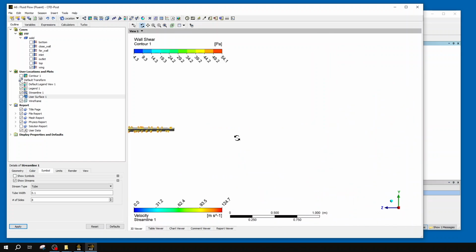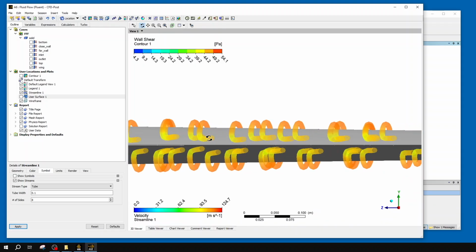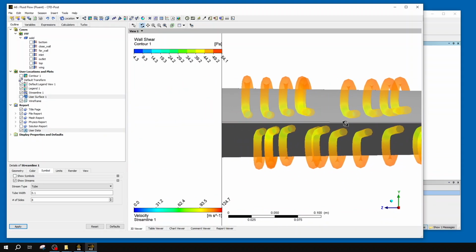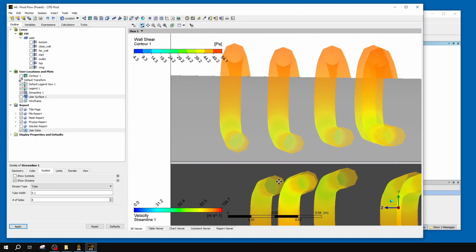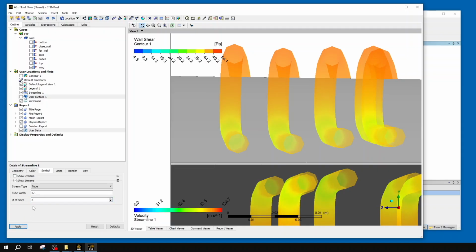These guys, let's hopefully say I can see them from the back. You can see what looks to be little circles, but in reality they're octagons, right? Number of sides. If I change that to 4, you can see they all turn into squares. So you can use these, and they can be beneficial. You just might want to make them thinner and either increase or decrease the number of sides based on yours.